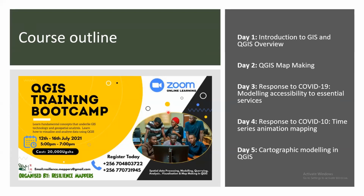Then on the second day, because I think most of us are familiar that the final output of GIS is a map, whether it is a web map or a printed map, we're going to take you through how you can produce a beautiful map using the QGIS software. Of course, things like picking the right color in case you're producing a given feature. Maybe your map is about terrain, maybe it is about population, what kind of colors should you choose to use? Or which scales can you use when you're producing that map?